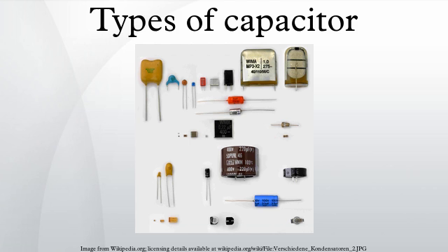Microphonics. All ferroelectric materials exhibit piezoelectricity, a piezoelectric effect. Because Class 2 ceramic capacitors use ferroelectric ceramics as dielectric, these types of capacitors may have electrical effects called microphonics. Microphonics describes how electronic components transform mechanical vibrations into an undesired electrical signal. The dielectric may absorb mechanical forces from shock or vibration by changing thickness and changing the electrode separation, affecting the capacitance, which in turn induces an AC current. The resulting interference is especially problematic in audio applications, potentially causing feedback or unintended recording.